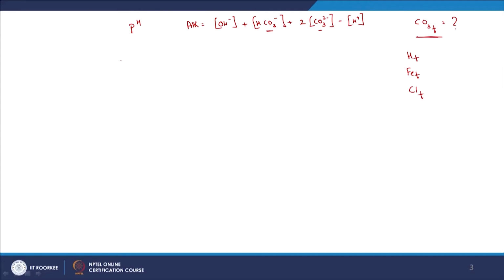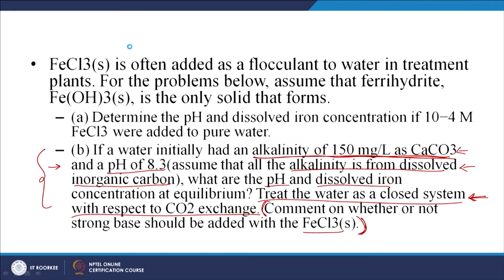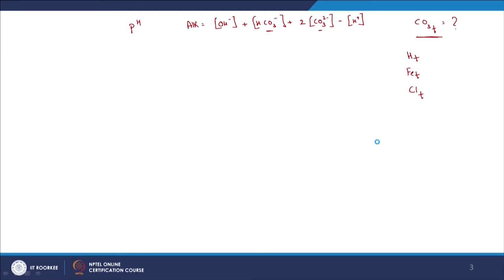So alkalinity, again, I know this particular value that was given. I think I can change the units to moles, molar units or equivalent units if required. And I think it is 50 grams per equivalent for CaCO3, and I can divide and get it in equivalents per liter. Anyway, alkalinity is a known value, and how can I express this equation?